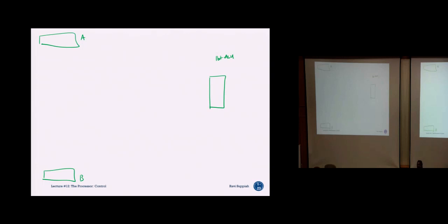They are the 2 numbers. It could have been your 2 registers, or 1 register and 1 immediate, you do not know. But you know that each of them is 32 bits. When these 32 bits are sent to the ALU, this ALU is actually a 32-bit ALU, correct? But this 32-bit ALU is composed of 32 1-bit ALUs. That means this is bit 0, bit 1, correct?